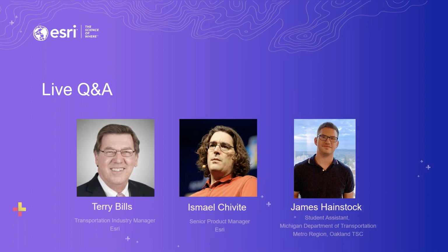To the second question, can I use ArcGIS Pro? You don't use ArcGIS Pro to configure a project. For that, you use QuickCapture Designer. It's actually much easier than it would be with ArcGIS Pro. However, you can use ArcGIS Pro to create the feature layers that will be used by QuickCapture. In fact, in the QuickCapture GeoNet place, we have a tutorial that describes how to author your feature layers in Pro and then build the project in QuickCapture Designer.